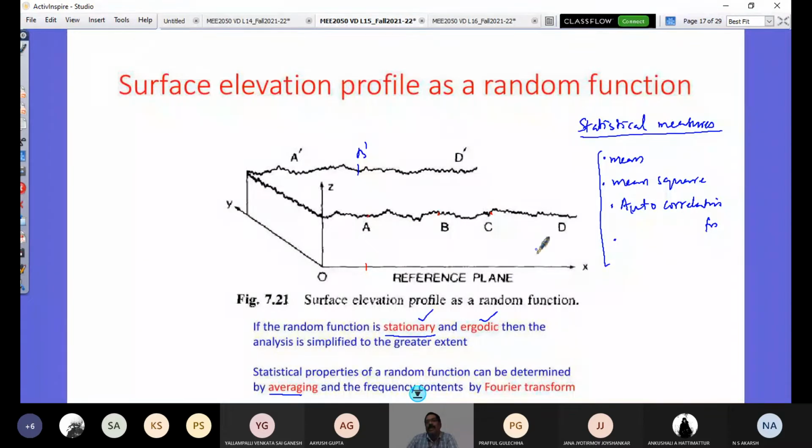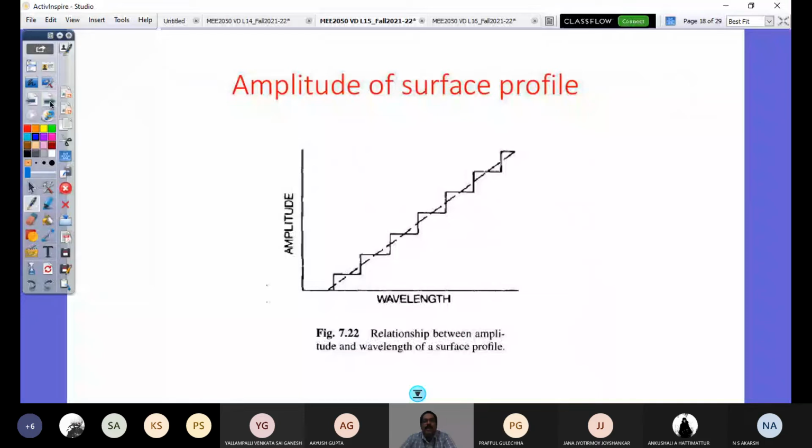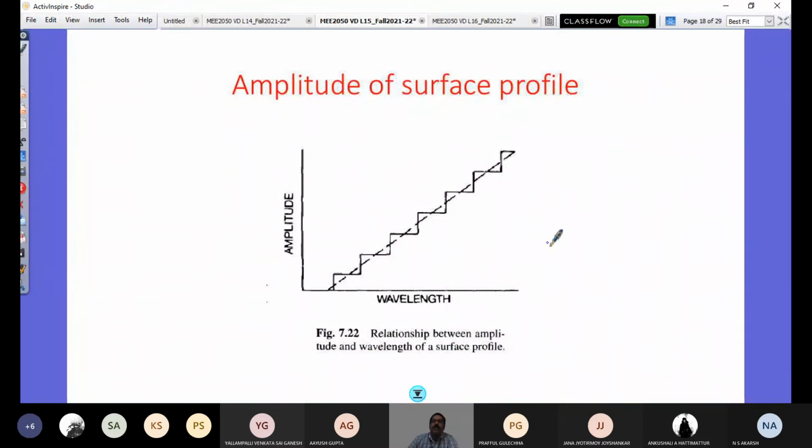That is how many cycles per meter, nicely, by help of taking Fourier transform of such profile variation as function of its distance. So that's the beauty of this mathematical tool. There are filters based on this Fourier transform. They automatically do it when you have this profilometer data. And then you would be able to do it. So to understand, let's understand now the amplitude of surface profile.